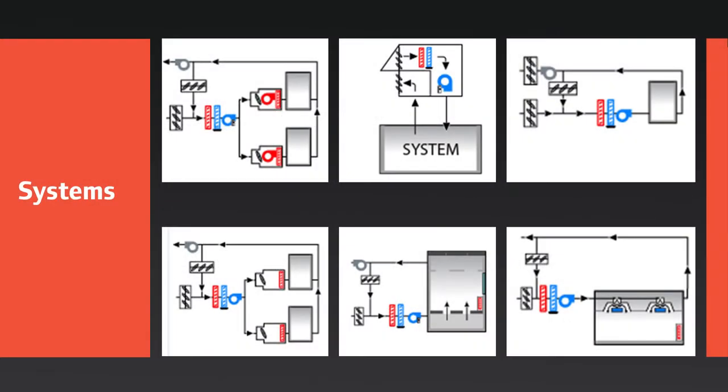The Systems section of the program represents the air-side systems that are used in conjunction with plants to condition spaces. The system is defined by its air path and the components in the air path as well as by zone-level equipment. The system is also defined by its temperature and humidity controls. Some systems have one large air handling unit with one set of coils that serve all of the zones on that system. Other systems only have a small piece of zone-level equipment to condition each zone individually. We will take a look at how to set up several different systems in this section.